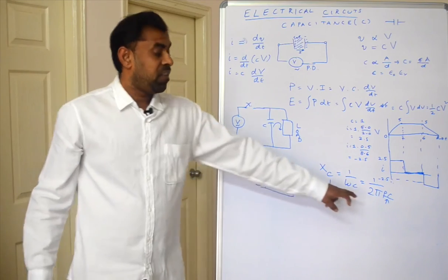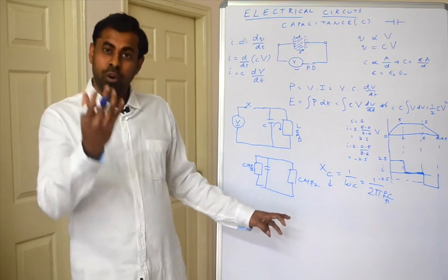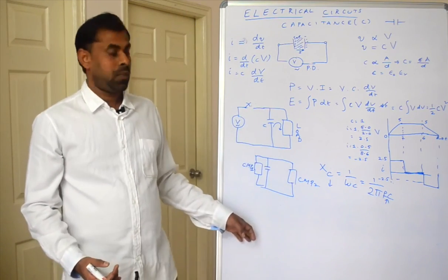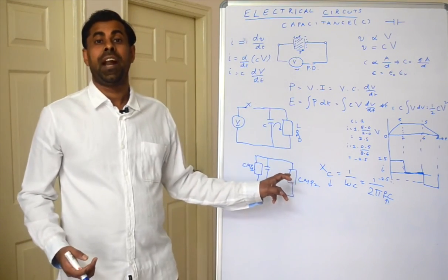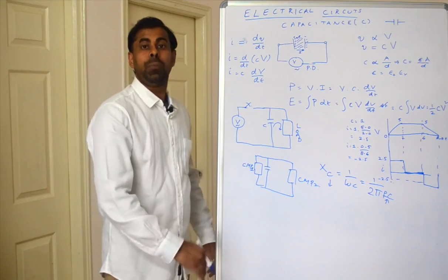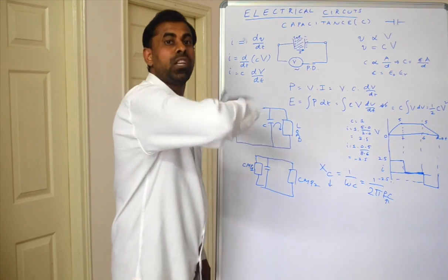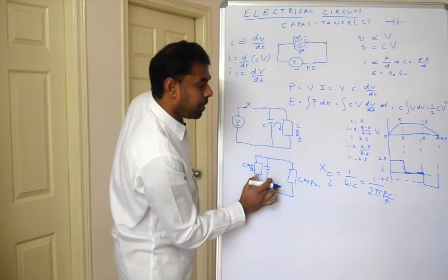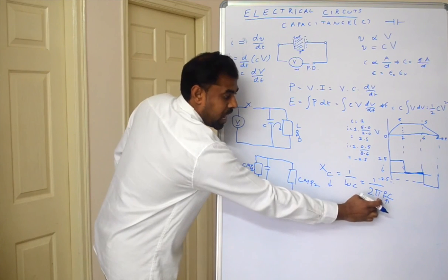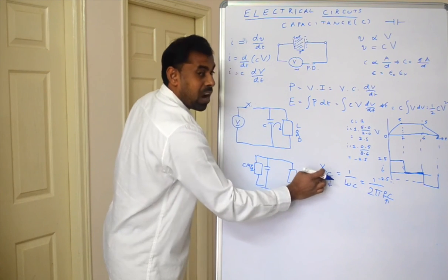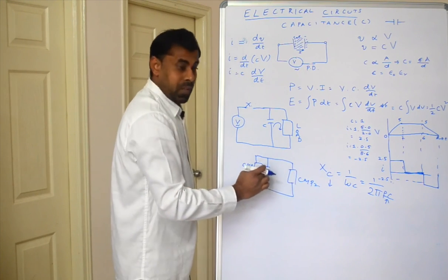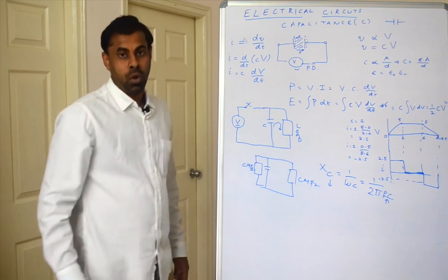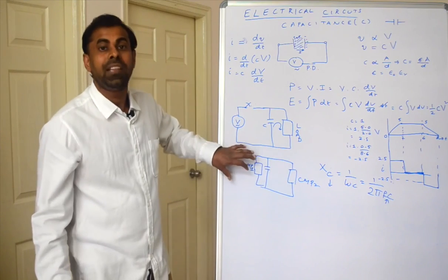That means for high frequencies it offers very low reactance so that it absorbs. If the frequency is low, it offers very high reactance and will not consume anything, so that passes to other components. In this application, for the high frequency components the capacitor offers a very low reactance, so it consumes the high frequency noise generated by this component.